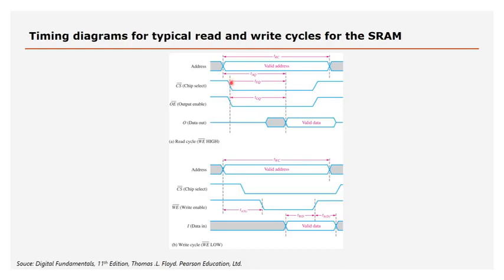Pull down the chip select to activate the device, and pull down the read line to indicate that it's a read action. The address is already valid, and then you just have to wait a little bit. This is the TGQ, a specific time frame you'll get in the data sheet, before the data is valid on the data bus.